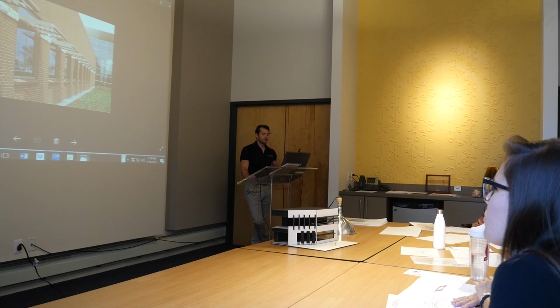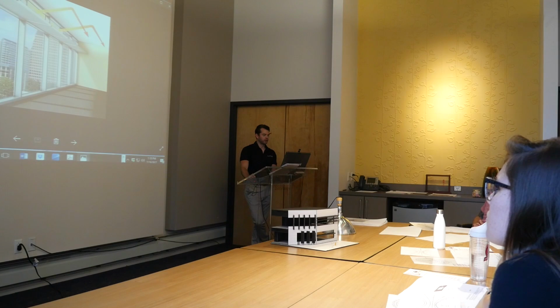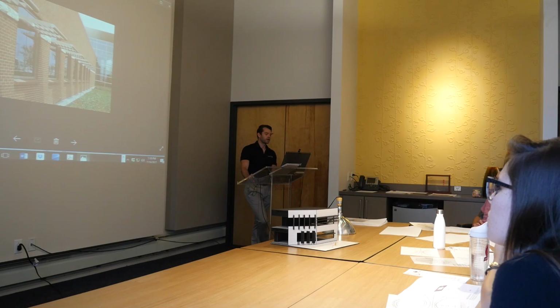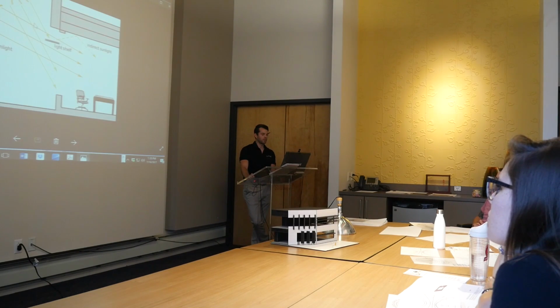Similarly, on a lot of buildings, especially schools, you'll see light shelves, and these do something interesting in that they're midway in the window. It shades the space where people are actually working, so it blocks your computer screen from getting glare. But on the inside of the building, on the top side, it bounces that indirect light further back. This is a pretty effective way, and we do that on a lot of buildings, to get light back into the space.